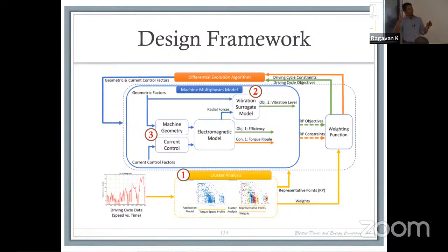And based on that, you can predict, now I have trained it for a certain number of points. After that number of points, the system can, even if you did not train it for a certain point, like a neural network system, even if it was not trained for that point, it can still tell you what the acoustic noise was. So yes, there is value, but you have to be careful in how you are integrating that into your model. Along with the frequencies, you would also need to integrate that initial design for the motor. So that then has relevance. Having a frequency model that doesn't connect to the electromagnetic model then has no meaning. Does that make sense at all?